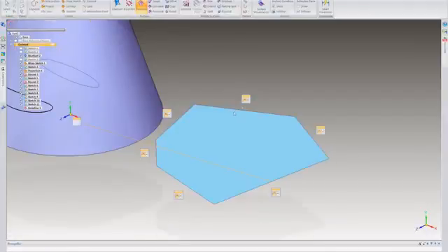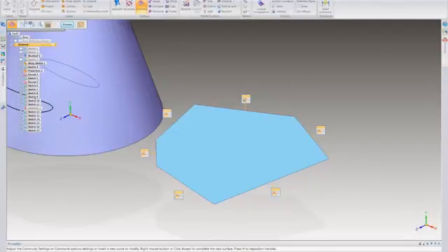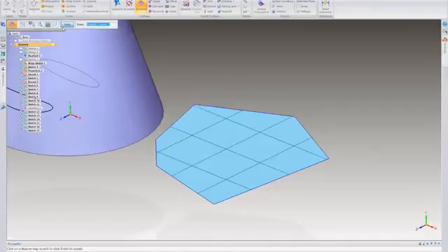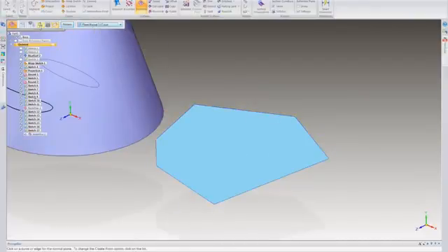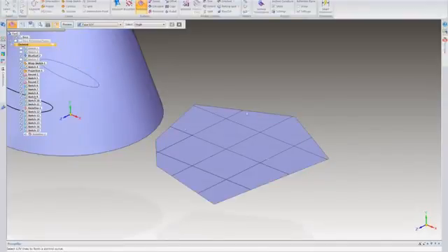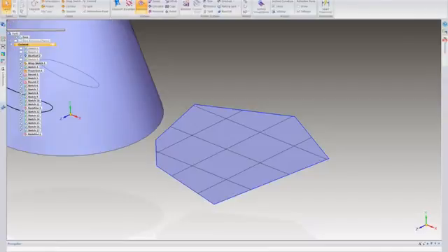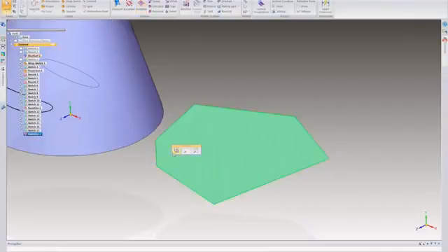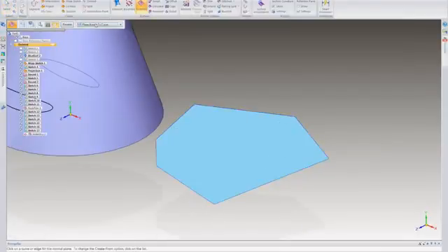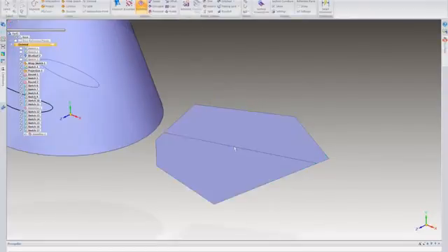Let's go back into it. And I'm going to create, there it is. There we go. So now I can create a plane normal to curve, or I can use my surface visualization. Right now I have it set to plane normal to curve. The face UV is what I was looking for. So basically all those points in space are now control points that you can manipulate. As you see, it actually places a sketch. I didn't go ahead and accept it. I apologize. Let me just do the single. I like plane normal to curve. Let's grab a sketch through there. There we go. That's what I was looking for.